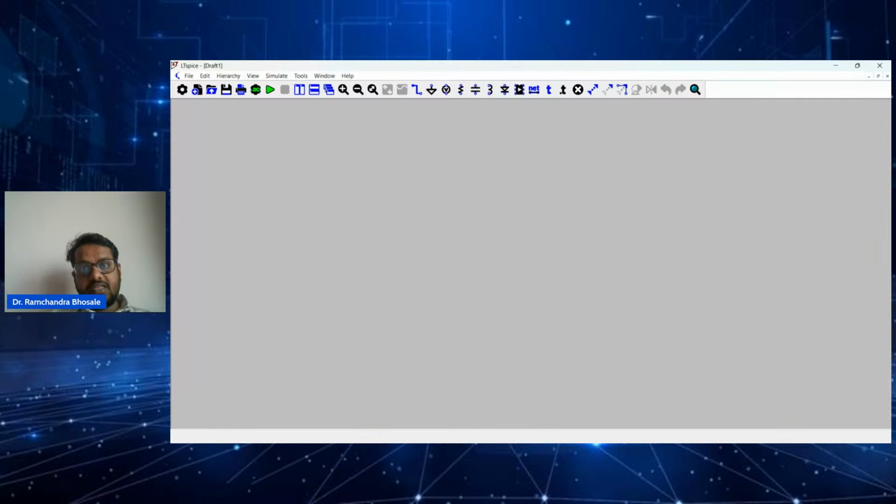But in this case, you can use the actual MOSFET model which you are going to use in the circuit. So here you can get the actual circuit behavior, not the ideal behavior. This is very useful for circuit simulation. But if you have to do a control block simulation, like simulating a generalized inverter with a control system, then you should use MATLAB. But for dedicated circuit simulation, LTspice is a good one.